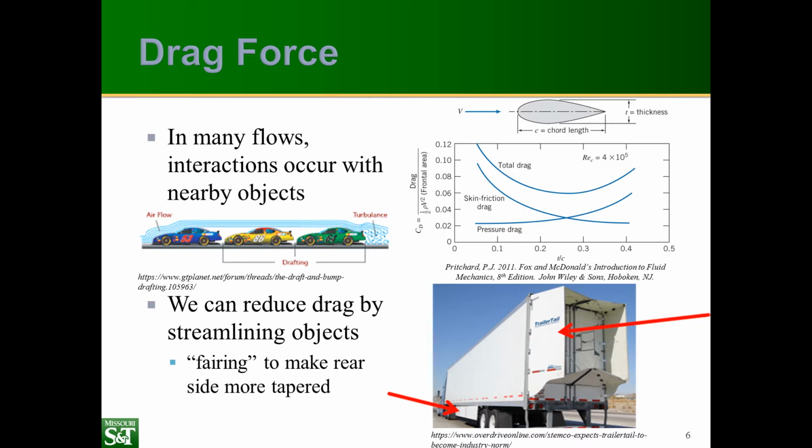In recent years, CFD has been used to optimize the front and rear contours of cars. This has allowed us to reduce the drag coefficient from about 0.55 to 0.3 or less, and in fact, it can be as low as 0.2 for some types of sports cars. And it's one of the reasons that many different brands or varieties of cars look very similar, because they've all been optimized to try to reduce the drag coefficient and reduce fuel consumption.